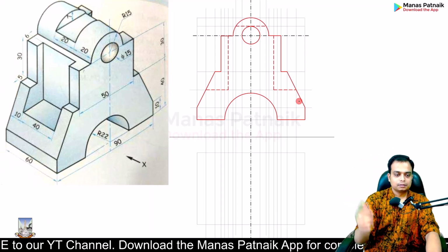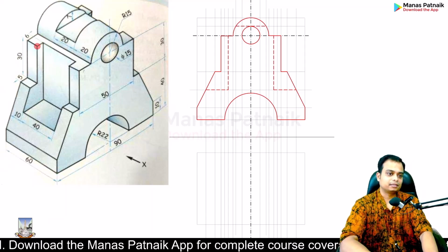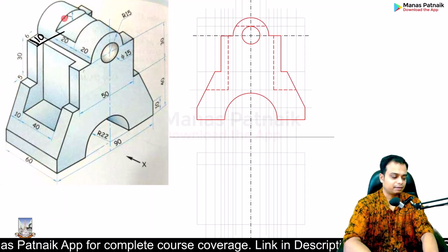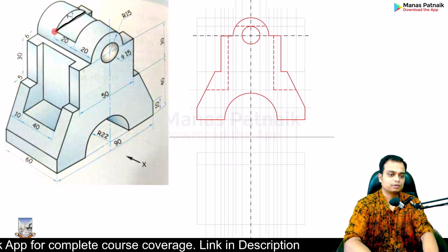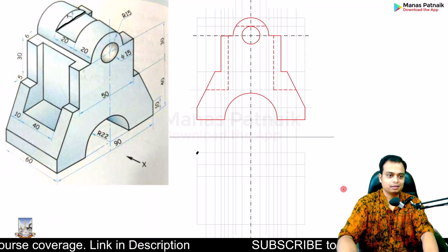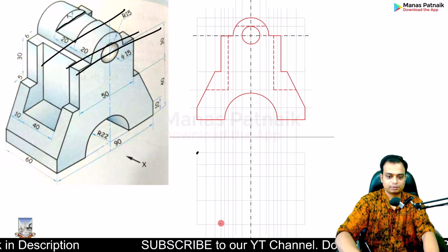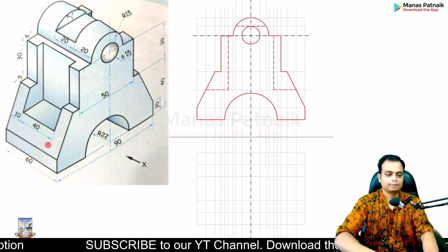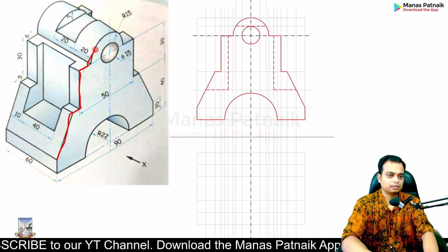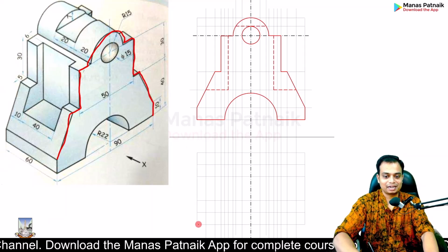Now, I think it's time to create the top view. For top view creation, you need certain lines. I mean, this is at a distance of, sir, this is 10 millimeters. So make it. At the same time, this line is at a distance of 20. So either from here you can mark 20 distance and make this line. And in the same fashion, there are going to be 2 more 20 and then 10, 10 this way. 20, 10, 10. Right? When you look at it from the top, this zigzag portion that you see, when you look at it from the top, will appear as a straight line like this.